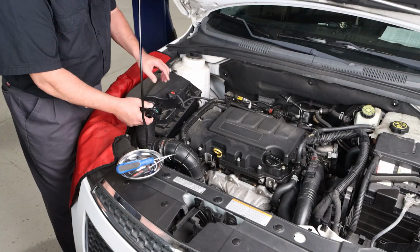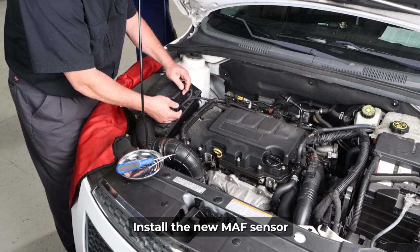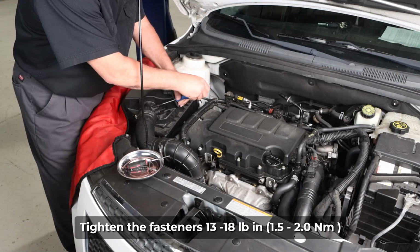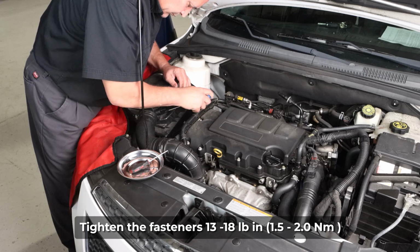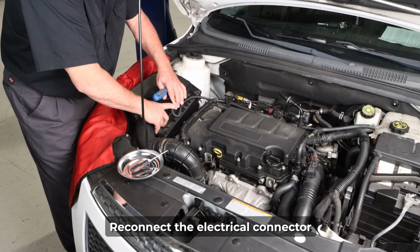Installation is the reverse of the removal procedure. Position the new sensor in the mounting location. Tighten the fasteners to specification and reconnect the electrical connector.